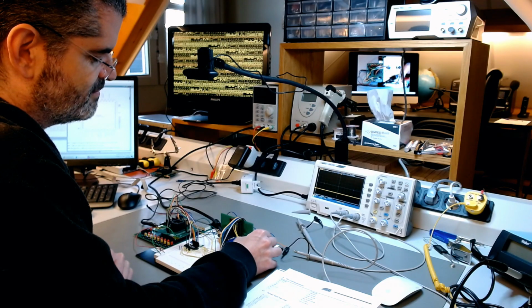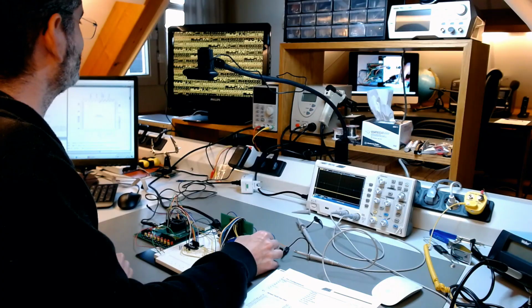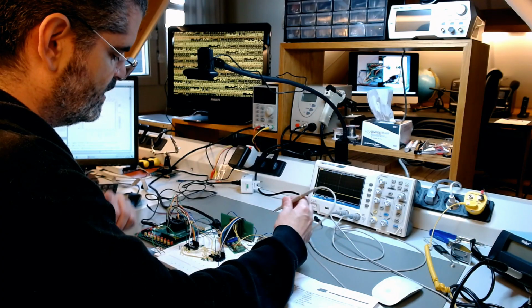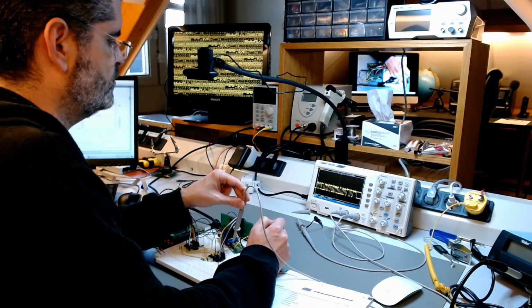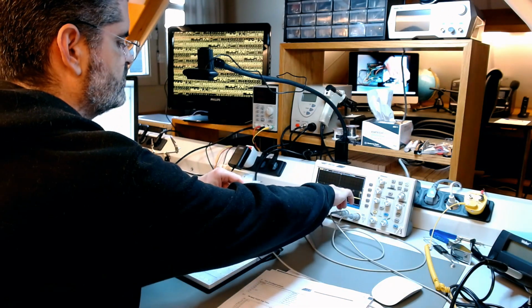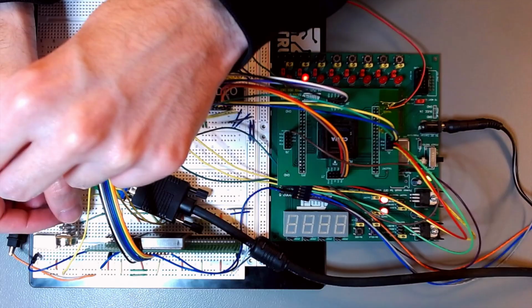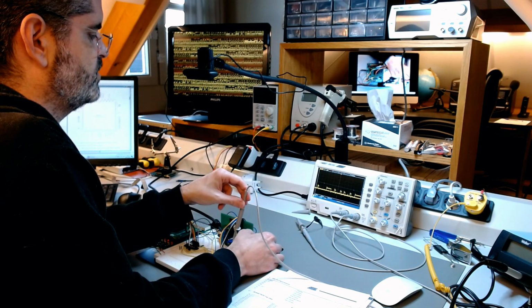Now I'm at zero resistance on the potentiometer. According to the standard, the color signal should have an amplitude of 0.7 volts. And now it has an amplitude of almost 2 volts. So if I bring it to 0.7, which is about here,